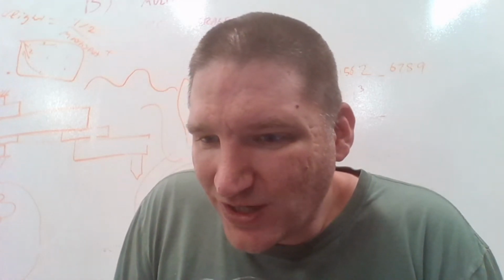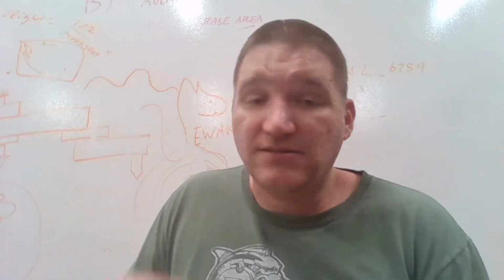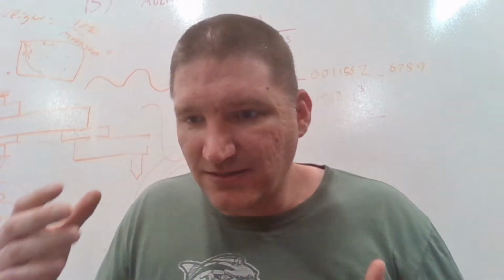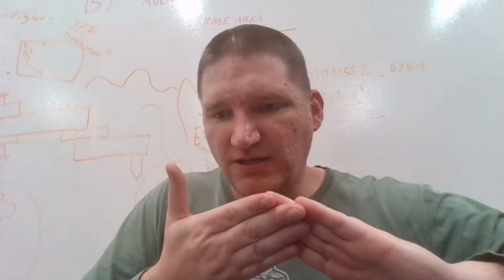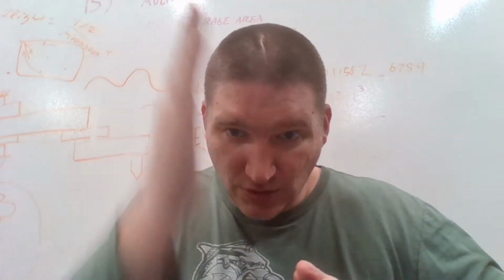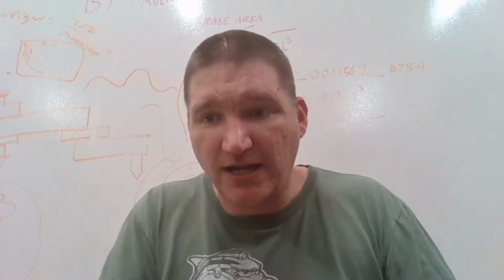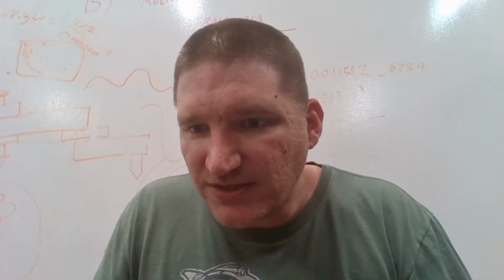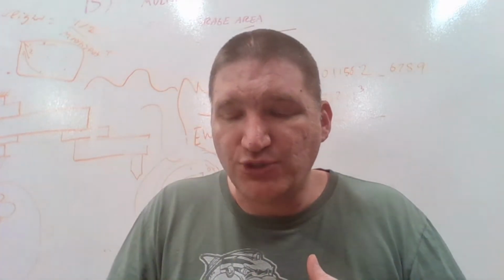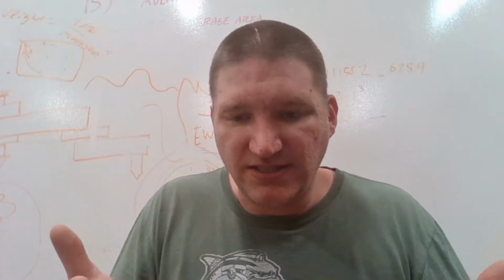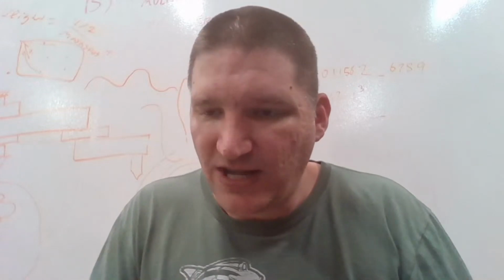Would the arms be better as a fork design instead of a cantilevered? Nobody asked about this yet, so that's a great question. I don't have the arm anymore, but the arm is what's called a single shear connection, where you can cut with one plane, and the arm will cleave off, and you'll have 2 arms. So one shear line. The way I'm doing it is called single shear, and you can do better by doing a double shear, where you actually connect, like you have one arm go around the other one, and that would have better performance.